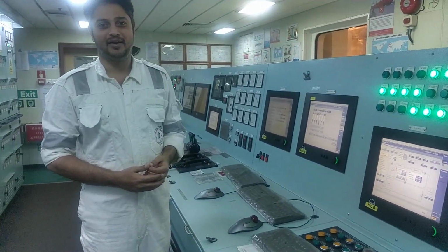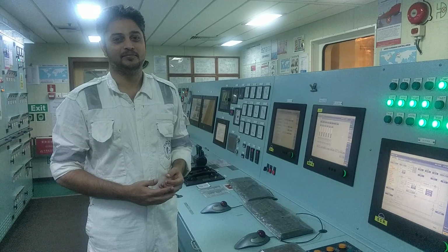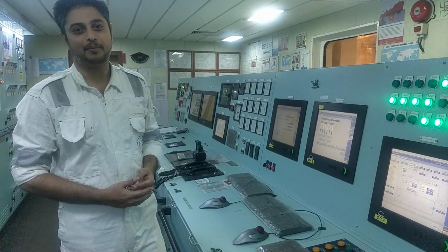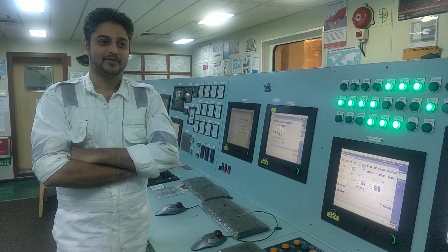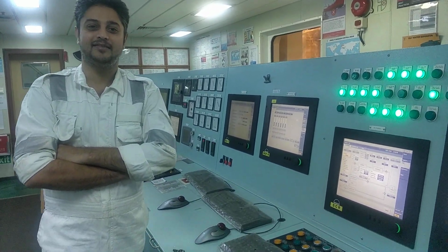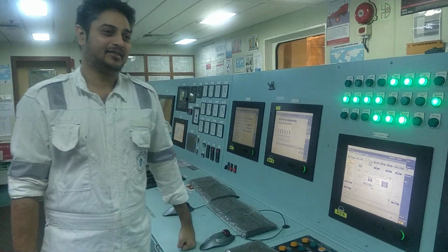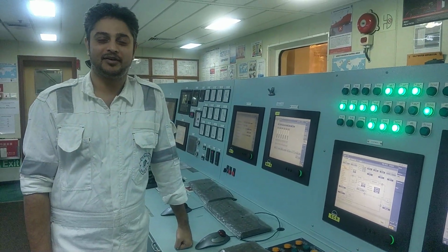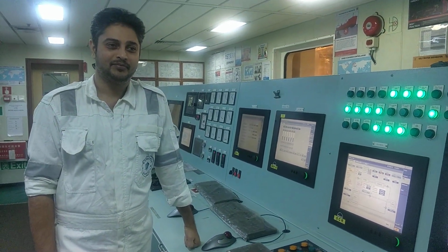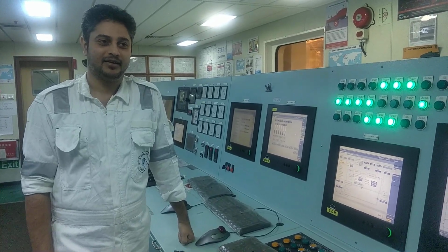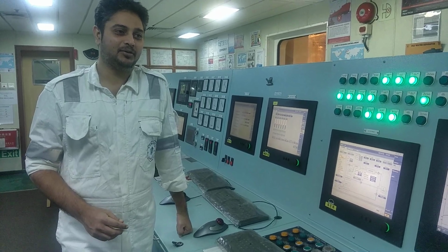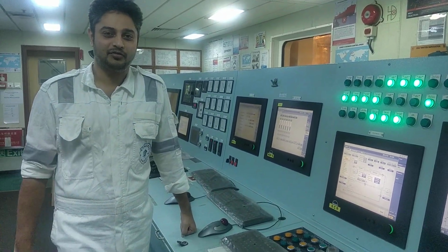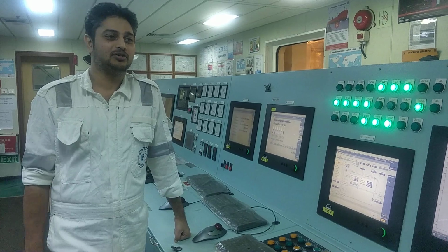In this video I intend to show you the installation of EPL on an ME engine. As a part of the EEXI requirement, the owners have decided to install EPL, engine power limitation. In our ship, they have limited it to 80.6% of MCR.